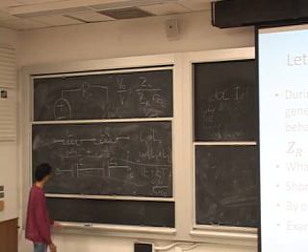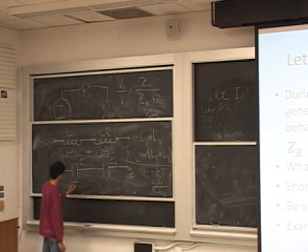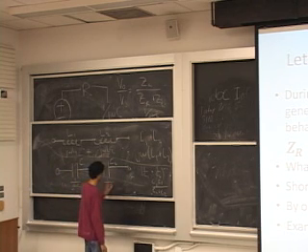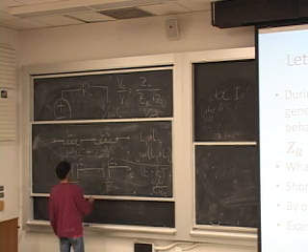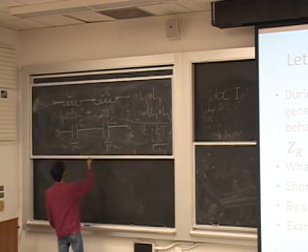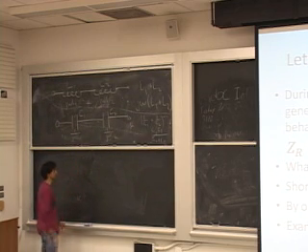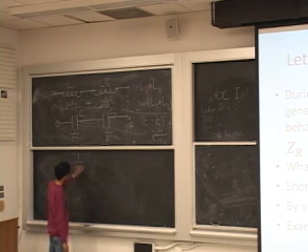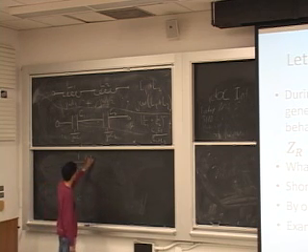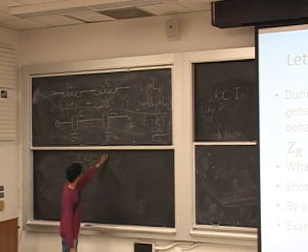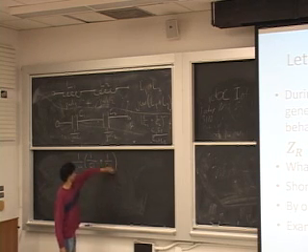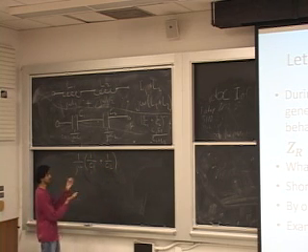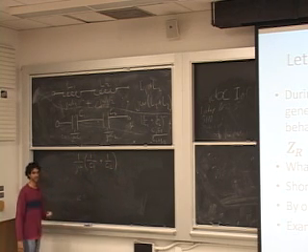Now with our impedance model, we have 1 over j omega C1 and 1 over j omega C2. If we add these together, we'll have 1 over j omega times (1 over C1 plus 1 over C2). So what is the net capacitance in this case?